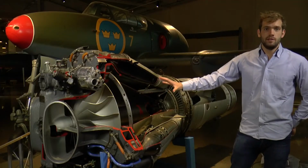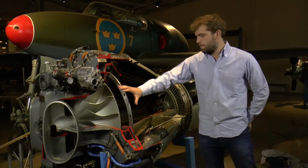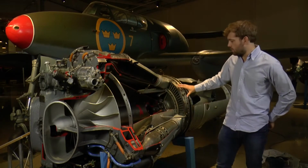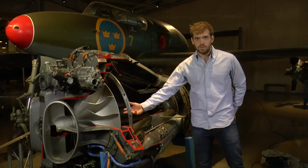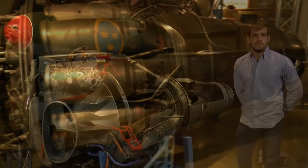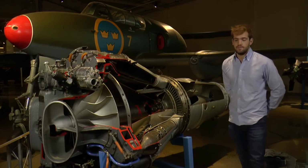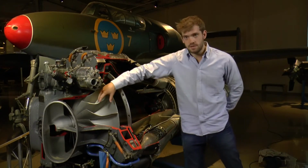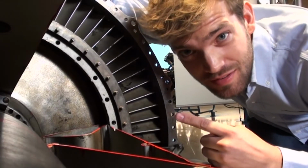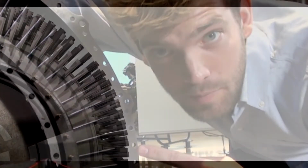Here we see the basic components of a gas turbine: the compressor, the combustion chamber, and the turbine, which through the central shaft powers the compressor. Turbines and compressors have different designs. In our case, the compressor is a radial design. And the turbine in our case is actually an axial turbine.